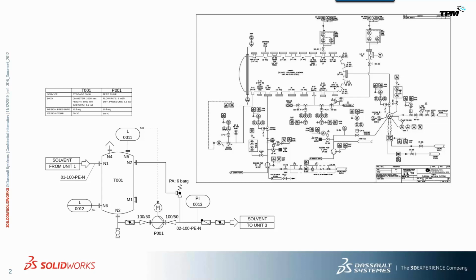Making a change to, say, a pump would require you to understand where in that project that pump is referenced, and we'd have to locate that and make the change everywhere. And that's really where the benefit comes in when using SOLIDWORKS Electrical to do these types of diagrams. We just change it in one place, and it's going to locate where that pump is located throughout the project and make the change and corresponding components that go up to it.